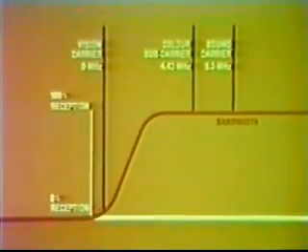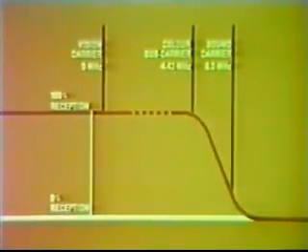It is important that the response at the color subcarrier frequency is similar to that of the vision carrier frequency. If the aerial bandwidth is incorrect, one or other of these will probably be low. An aerial chosen for the correct group of channels in your area should be used.